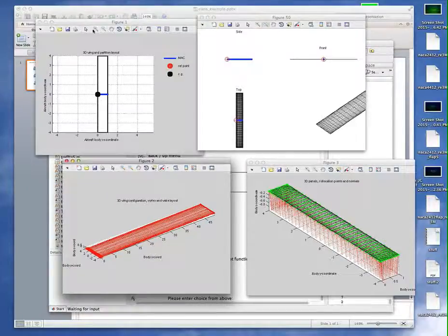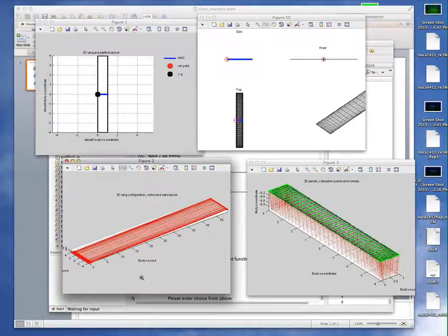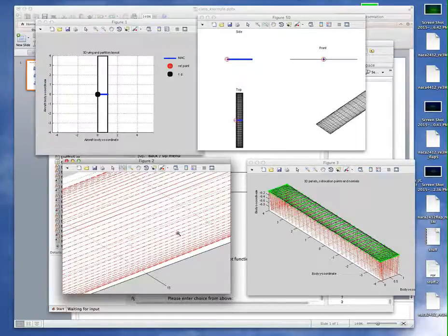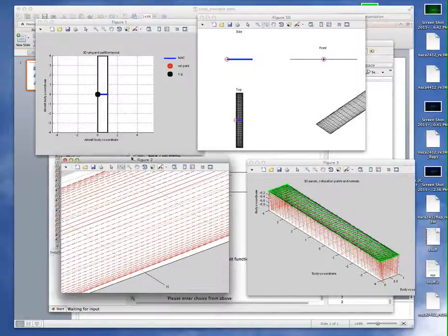This one down here, excuse me, shows you the wing, and these are the trailing horseshoe vortices sketched behind it, established by essentially 20 panels and 20 panels on the other side of this wing. And you can see how even these horseshoe vortices are clustered more towards the wingtip, which is where you have most of the vortex roll up.